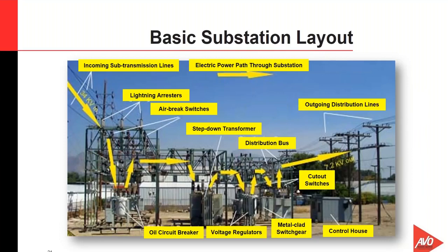We've got a 34K line coming in through the transmission lines, sub-transmission lines, goes down through the lightning arresters, through the air break switches, down through the oil circuit breakers for protection, and it goes back into the step-down transformer, through the voltage regulators, hits our metal clad switchgear distribution bus, cutout switches, all controlled through the control house inside there, and it goes on out to distribution lines.